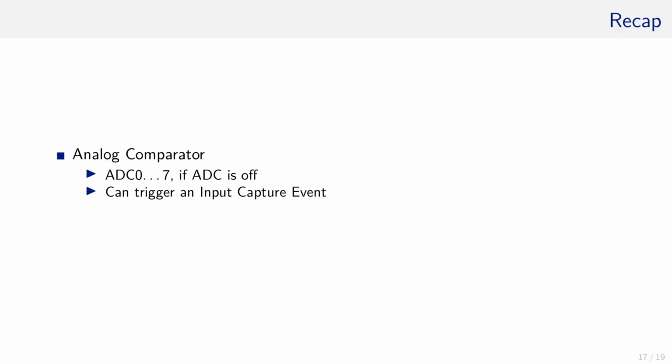Using the analog comparator instead, the calibration can be done by applying the required voltage to AIN0 and adjusting it till the comparator output changes at 25 degrees. In addition, instead of sampling the data in time intervals, which is similar to polling a register, my program can do something else, or even sleep and save power, since it is getting informed when the temperature crosses 25 degrees. No need to sample anything, since I'm not interested in any value or information other than when the threshold is crossed.